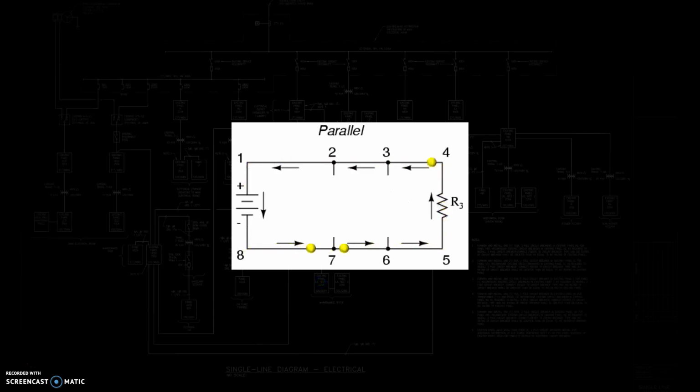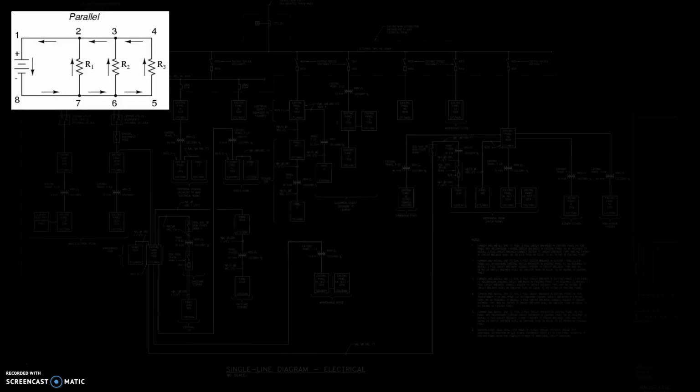We can even remove two of the three. Effectively, if you forget about those first two, this is simply a circuit with one element or one load. Another good thing to keep in mind is that every one of those elements or loads has a direct path right back to the source. We have these sides of the ladder, if you want to look at it as a ladder. They connect all loads back to the source directly. Keep that in mind as we learn our different calculation rules.